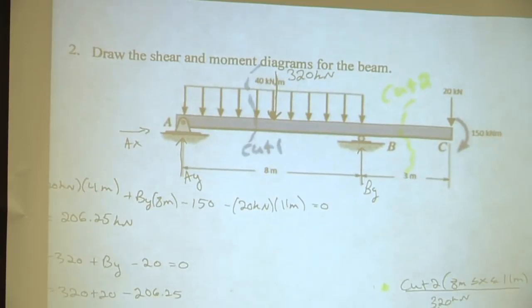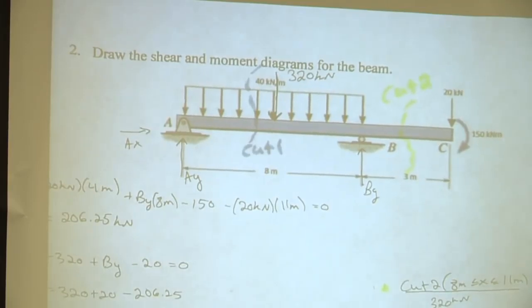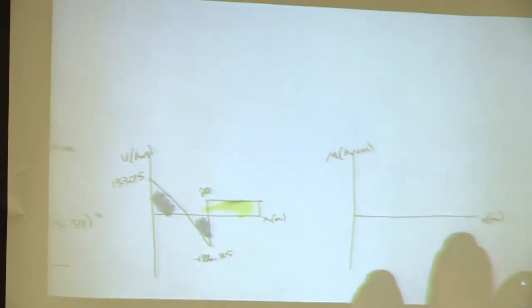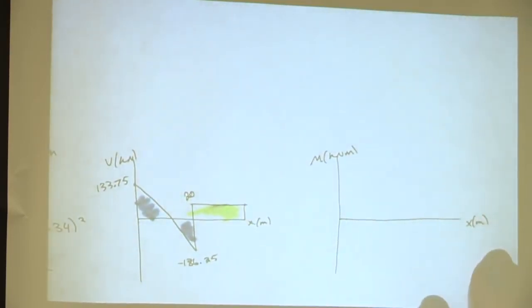Okay, so moment is bending moment, and what is located at A? Oh, a support. A support reaction. So can it bend at A? No. So that's one way to check, make sure that it is 0. Okay, so then where do we go from here?